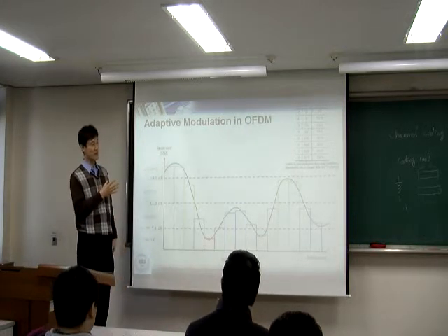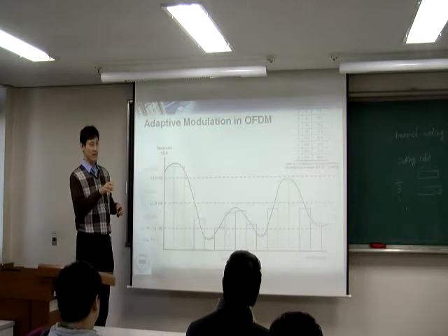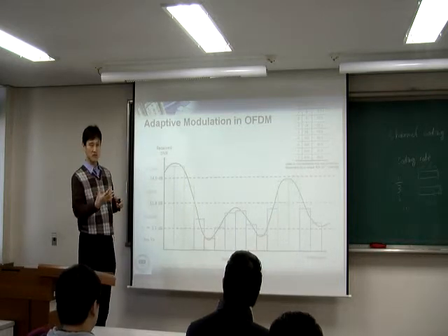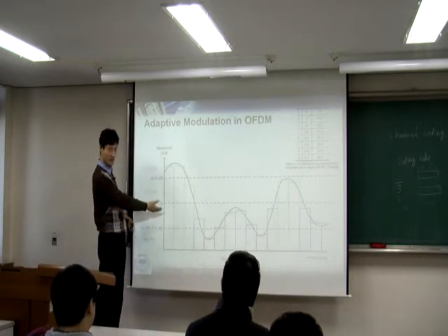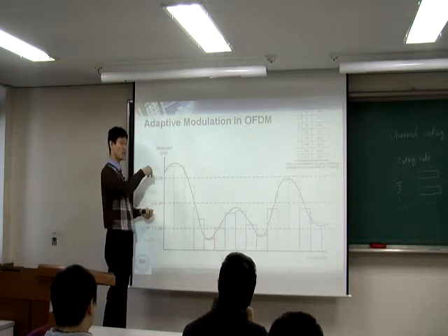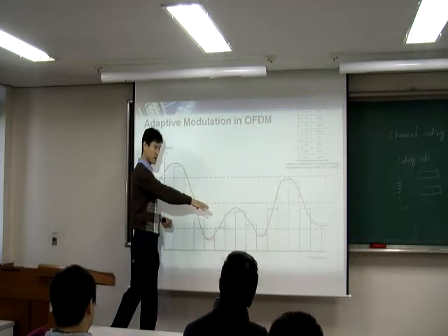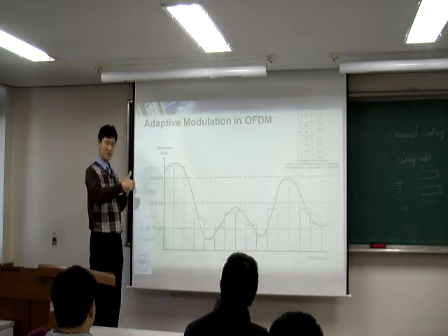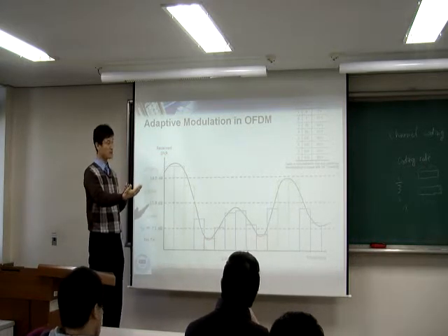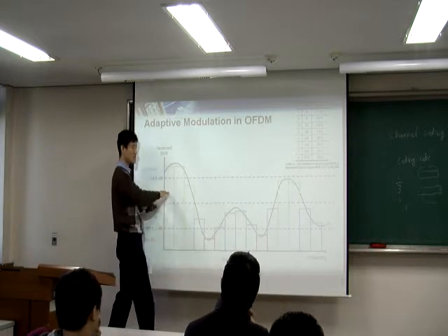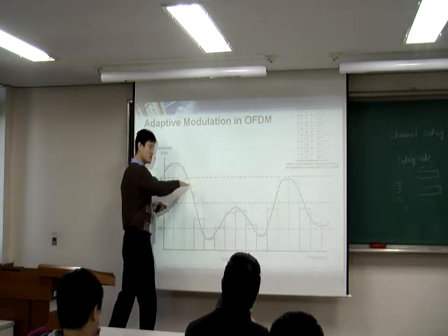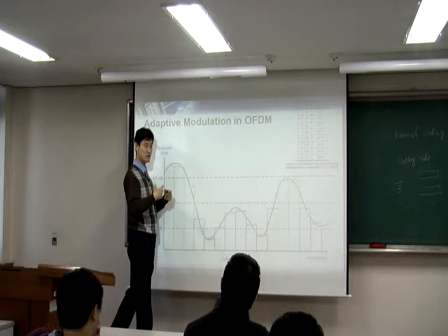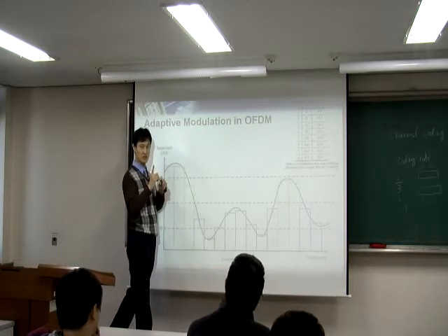So what they do is apply the FFT to go to the frequency domain, like this one. And then they try to load some information on the frequency domain. What they realized was that since you have multiple intersymbol interferences, that basically means your channel condition is never flat. If it was flat, then your channel impulse response would already be an impulse, which means no symbol interference.